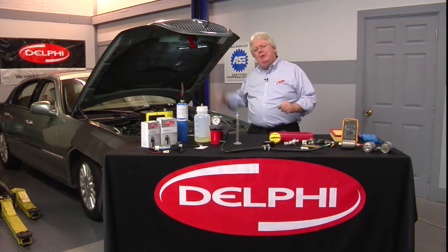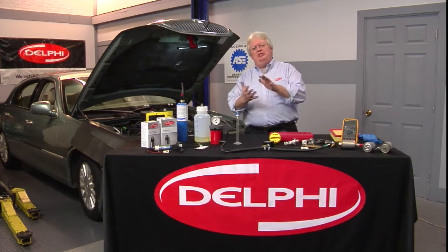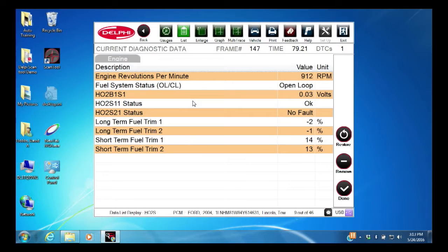Let's go ahead and start it up, and let's watch our scan tool PIDs. I've refined them down from my O2 customized list. I want to look at RPMs just to see what she's doing. I'm going to make sure she goes into closed loop, and I have no O2 sensor faults. We won't run a fuel trim monitor unless we've got good O2 sensors. So no faults, status okay, front and rear O2s, pre and post catalytic converter.